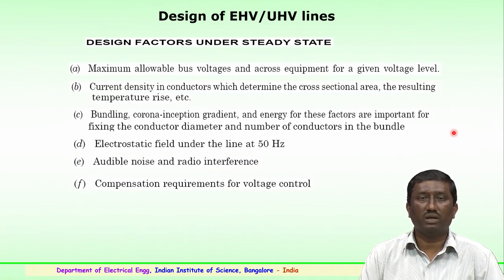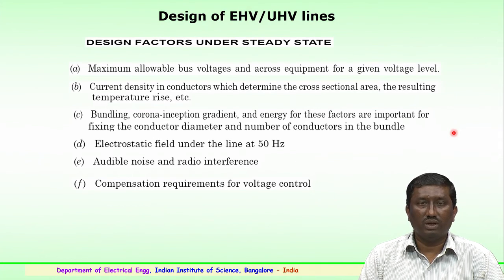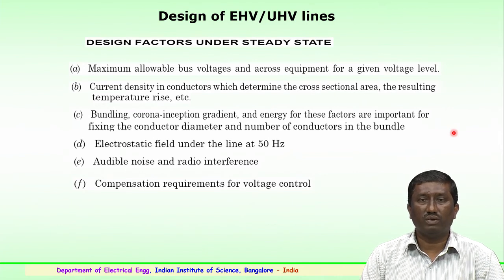So, that is the reason why the minimum noise generated by the samples has to be mandatory as per the 400 or 765 kV levels. Typically 55 or 56 decibel noise is allowed for the transmission system. For a radio interference of 400 kilovolts and above, 1000 microvolts or 56 dB is the tolerable limit, and it should not increase more than 60 dB, that is 1000 microvolts is very important. So, these conditions have to be considered for the design of the conductors or the hardware which are being used for the towers.